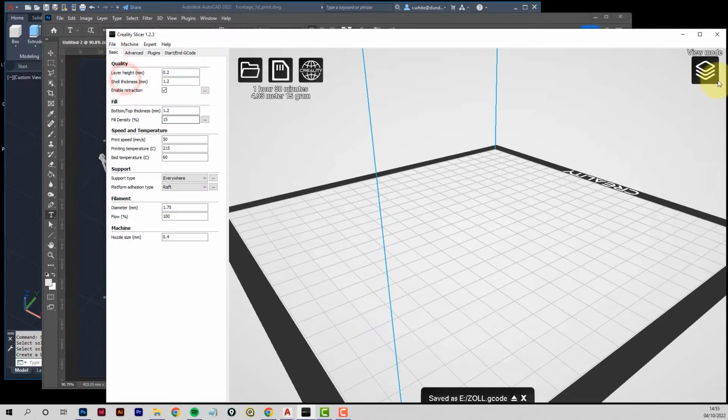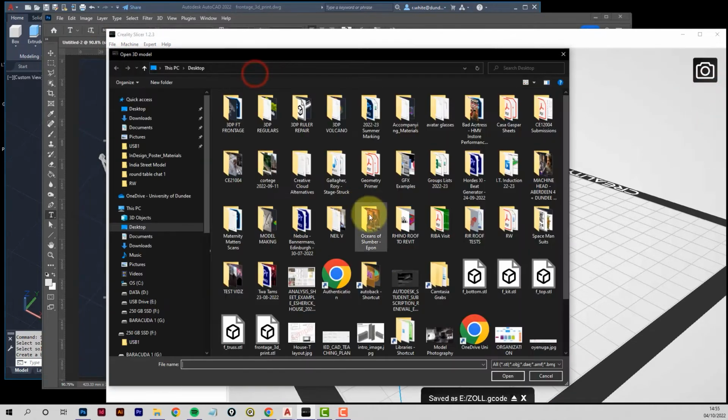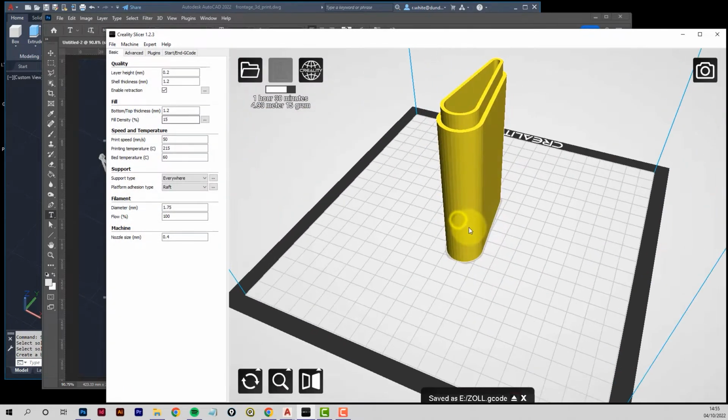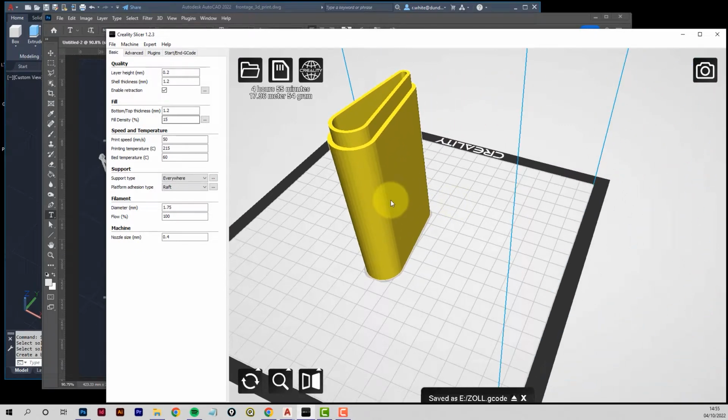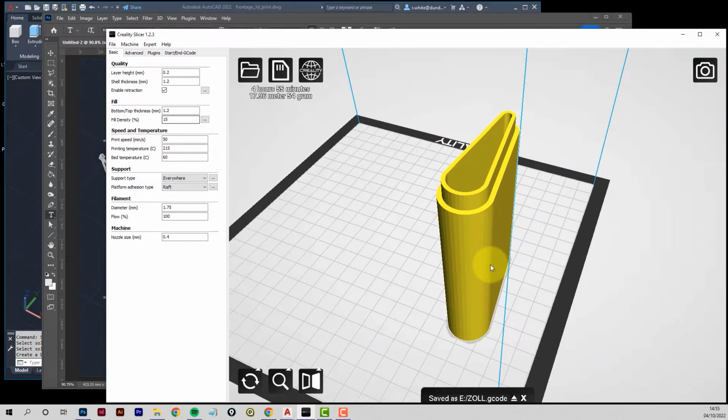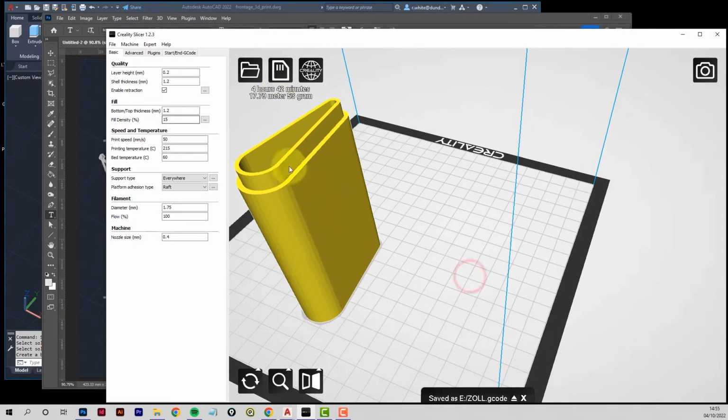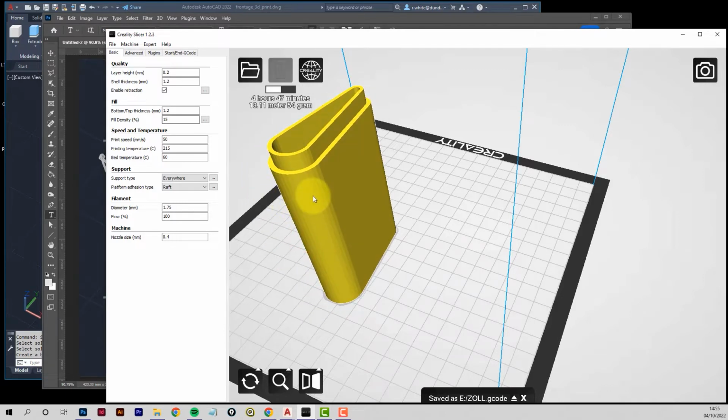So we'll clear the platform, and let's load one of the other portions. So let's say F bottom. So this is the bottom portion of the object, of the column. Okay, so you see here we're about 4 hours 50 minutes, 4 hours 55. Depends where you put it on the base. You get slightly different time depending if it's close to the origin. So the time varies just slightly. Okay, and this model is faceted. It's not a smooth model. It was unintentionally so, just to make it less heavy duty for visualization.